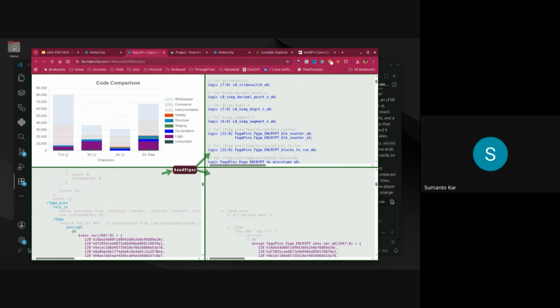Thanks. Someone is asking, can I transfer the Verilog code I generate here into standard FPGA development tools? Yeah, you can. TL-Verilog is a language extension. Any TL-Verilog constructs just convert to Verilog constructs. That's your Verilog code that goes through your FPGA tools. Basically, you can write in TL-Verilog and then send it to SandPiper SaaS, and it gets converted to Verilog. So yeah, you can use it that way.